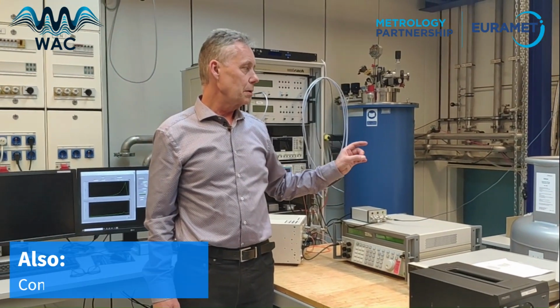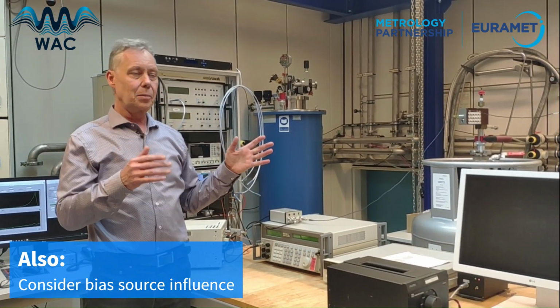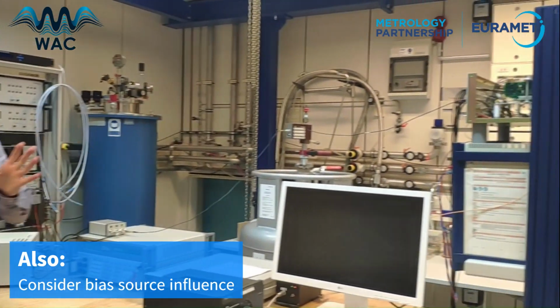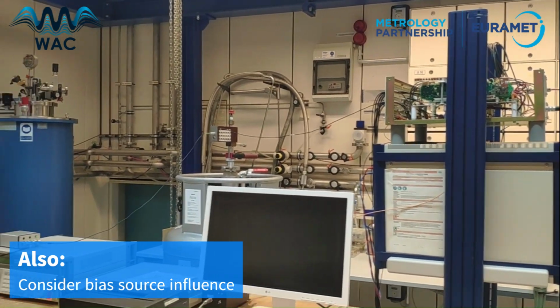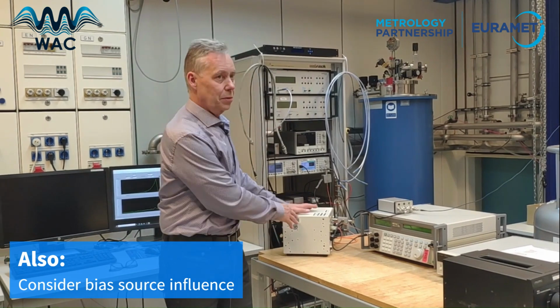And we also have to consider that the Josephson system is not just an isolated system. It's connected to a bias source which also gives a capacitance to the earth. So there's another path through the earth also to this digitizer.